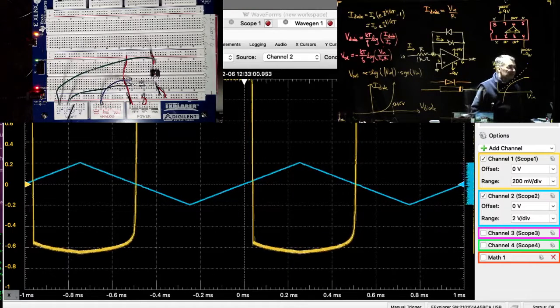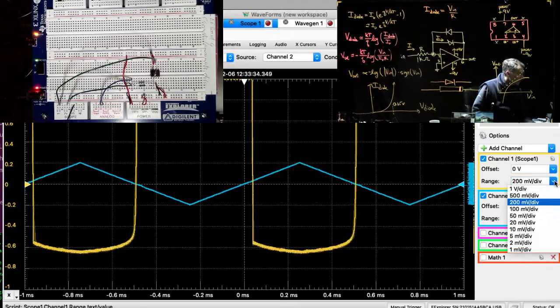I think it looks a little funny because the op amp goes a little bit nuts, because the negative feedback path is broken once the voltage flips sign. So that's why we see something that looks a little funny down here. When the output wants to be positive, there's no feedback anymore, so I think it just slams all the way to the limits of the power supply. I'm making this up as I go, but we could just take a look at that.